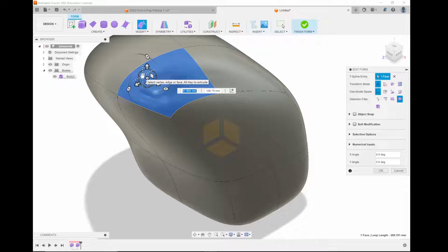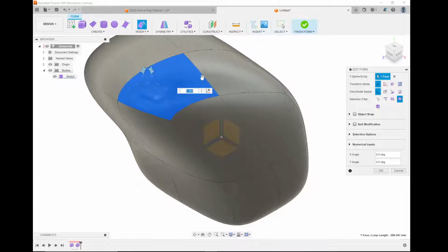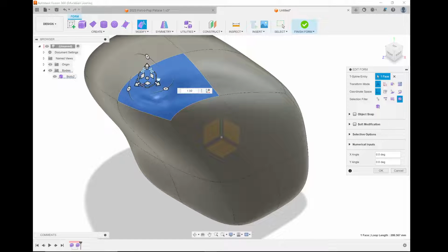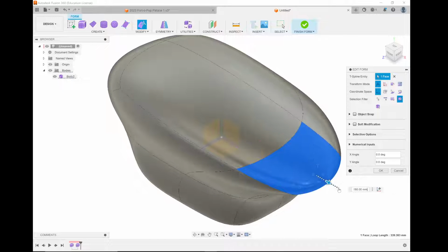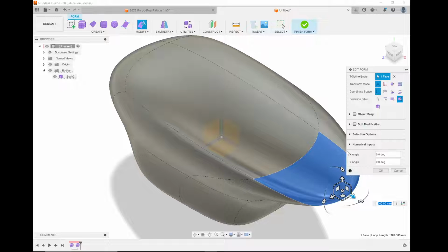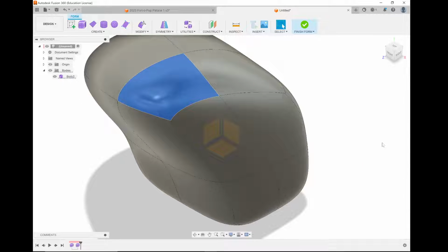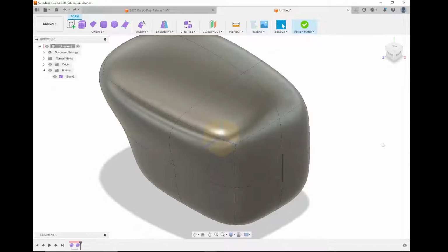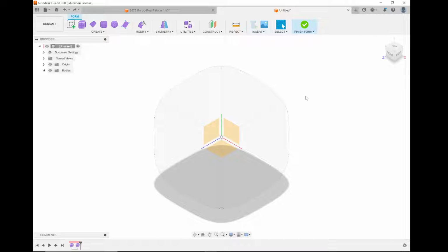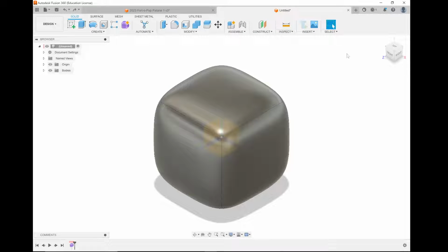For the purposes of our lamps that we're going to be using this for next year, laser cutting this won't work, but if you want to 3D print an object, this works quite well because we can turn this into an object that can be 3D printed. You can't really do this type of editing with the non-form tool of Fusion, but you can get any particular shape that you want and modify it. I don't want this for my particular shape, so I'm just going to get rid of them and go back to the form I have here.